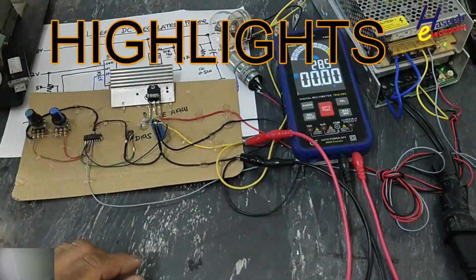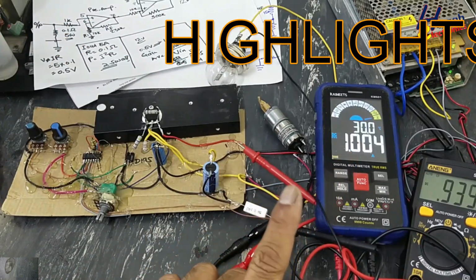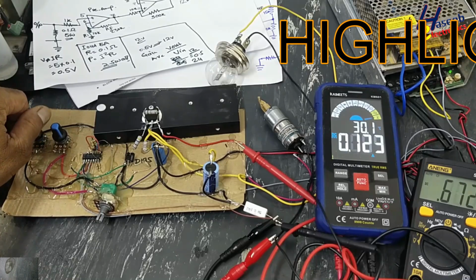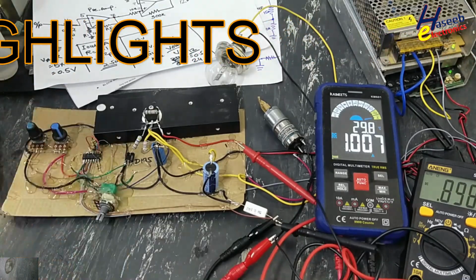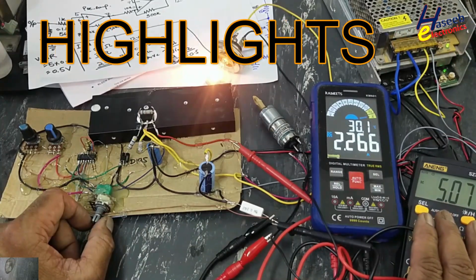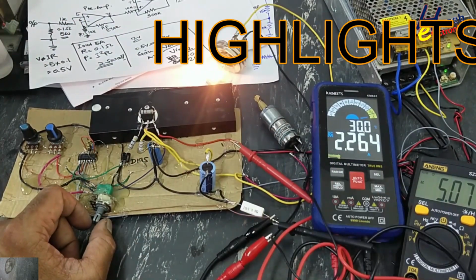Let's control the current now. Now our power supply is in 1 ampere constant current. If we want to increase the voltage, it will not increase because the system is in constant current mode. At 5 volts, these two items are drawing 2.265 ampere current.